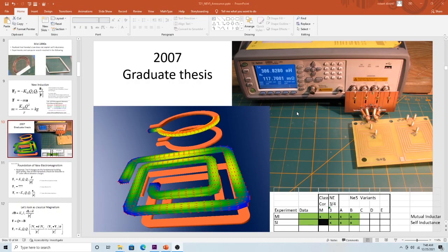A lot of the other prior art that I had seen was empirical models where they measured a bunch of things and did some empirical work. The only prior art that was field-based that I could find was a thing called partial inductance. But partial inductance violates vector magnetic potentials. It is not classical theory. In my graduate thesis, I go into great detail about partial inductance, and I also show you that partial inductance degrades when you start getting to curved inductors, like this loop inductor here.